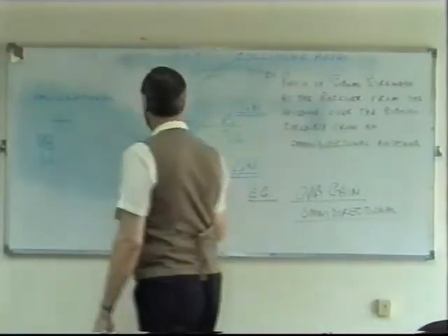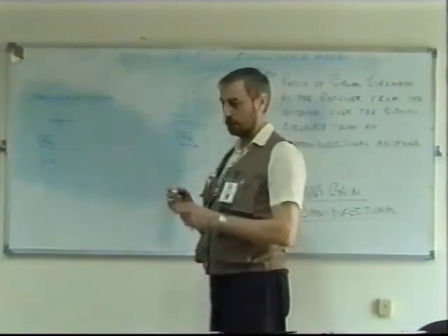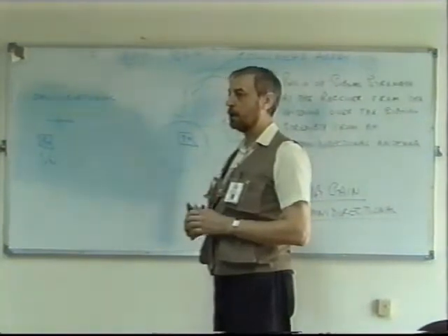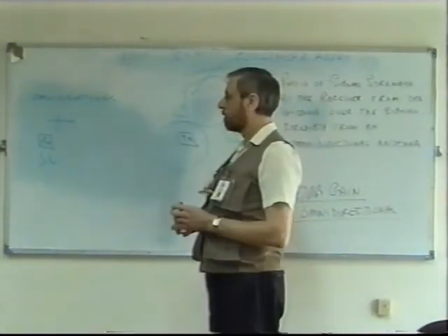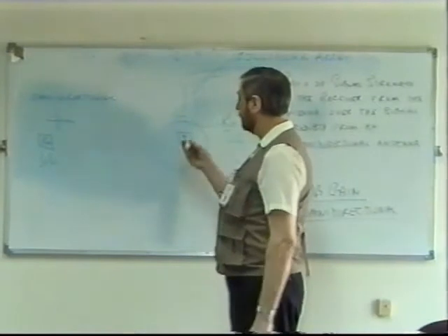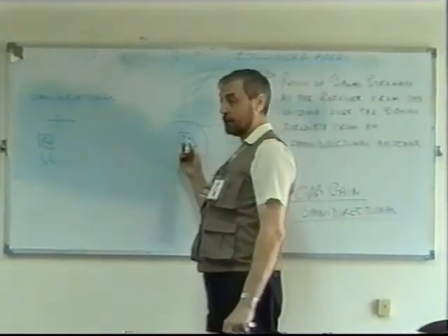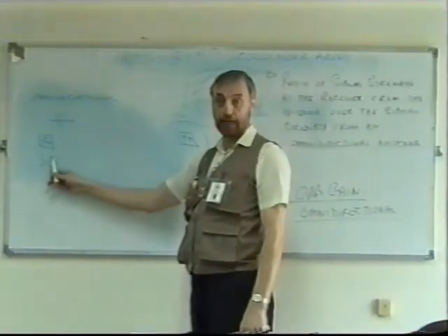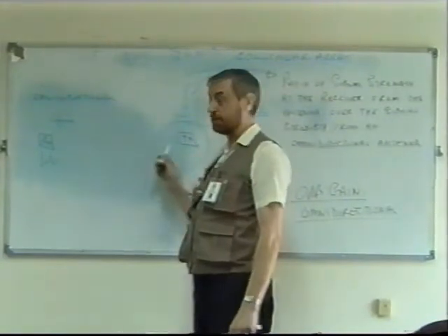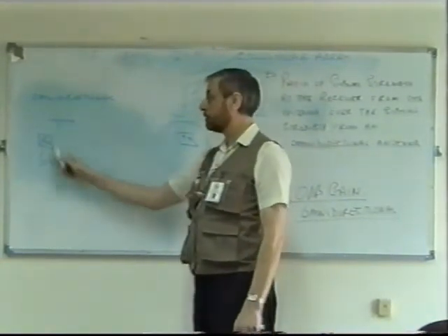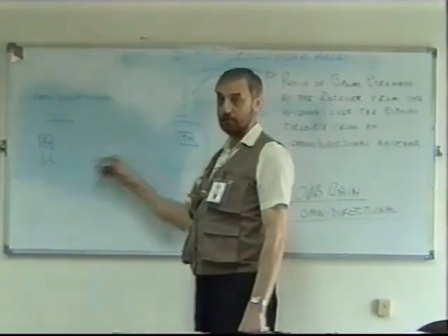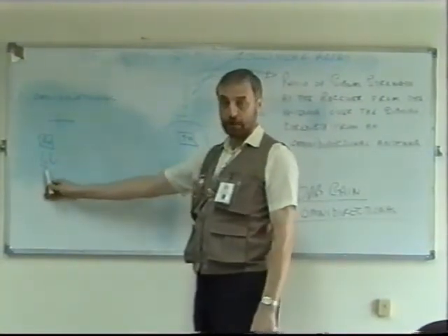But when we use the dipole also for that transmitter, at the moment I've not said what we've used here. It could be anything. If you use a dipole, will the power be the same or different? Well, obviously, if I change the type of antenna I use here, I will also change the power here. For instance, if I make this more directional, then I'll increase the power here; make it less directional, less power.